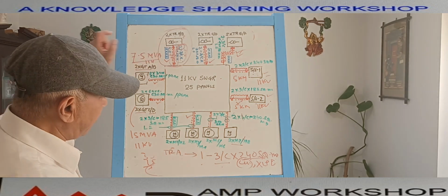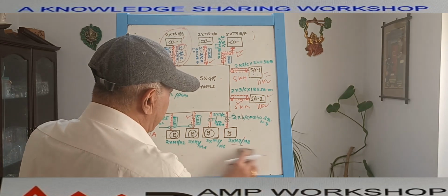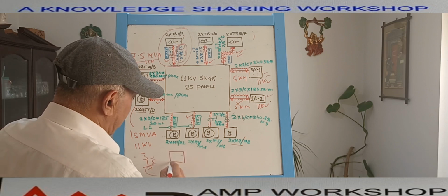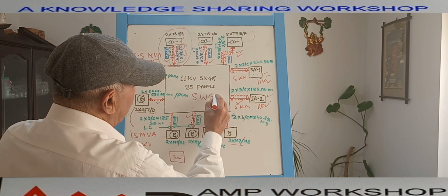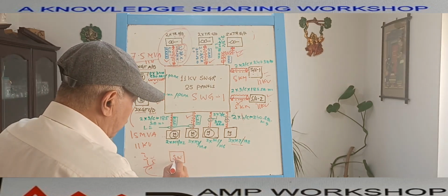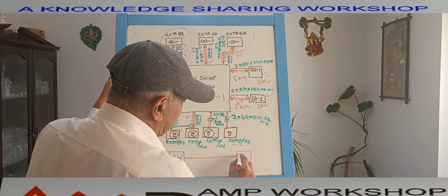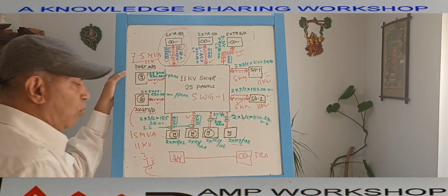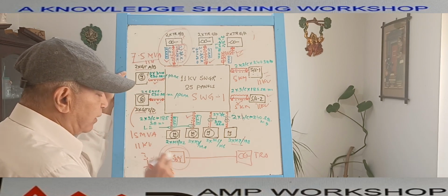Then this cable should have a tag to identify it. How will this cable tag be made? There are two equipment being connected. One is a switchgear. Suppose this switchgear tag is SWGR1. This switchgear 1 is connected by the power cable to whom? Now this transformer TRA, right? So normally the power cable originates from here. Actually, this is the source.